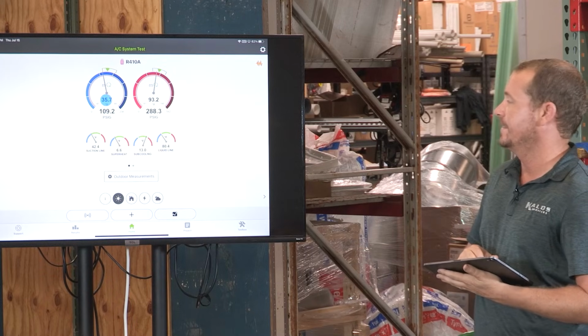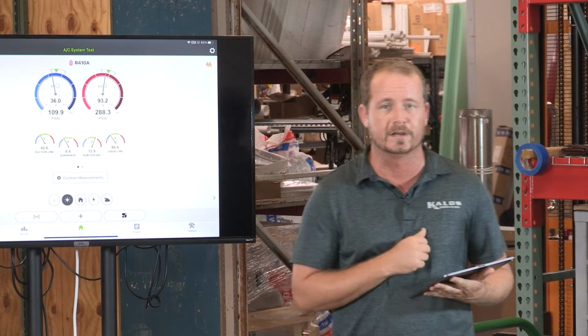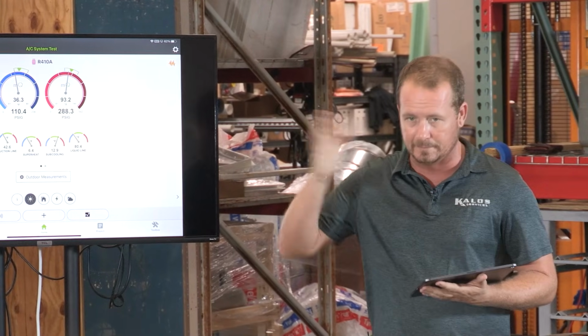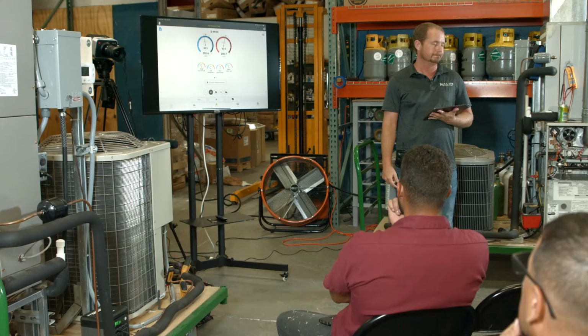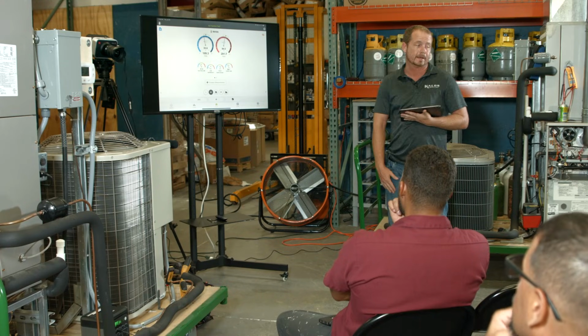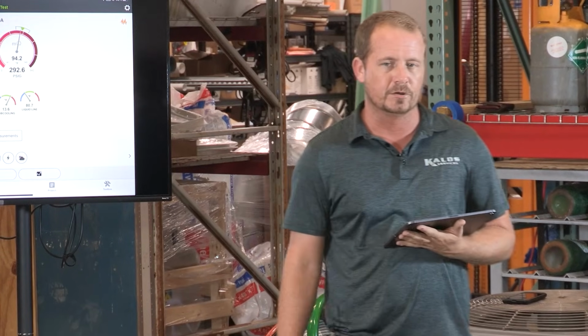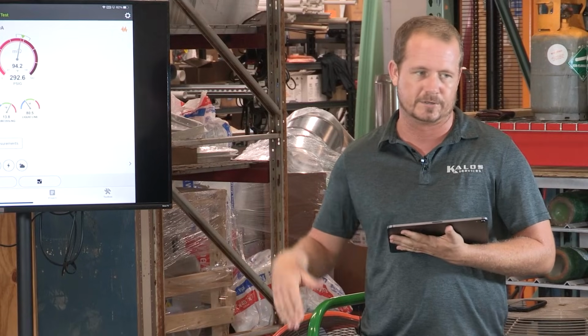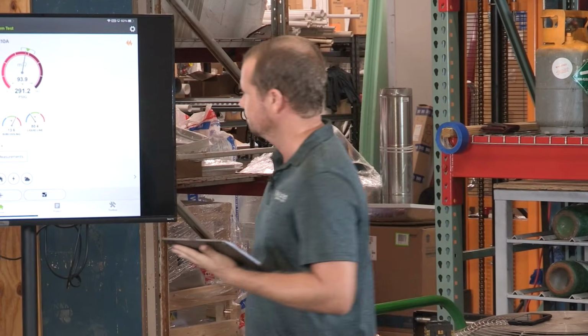But even then, just getting your evaporator coil to 32 degrees, it's not going to freeze like that. It's got to get below 32 degrees, a ways below, before it's actually going to start freezing. It takes runtime. Which is why you'll have units that don't freeze during the edge seasons, and then when the summer comes along, they'll start freezing just because they get longer runtime, long enough for them to stay frozen.